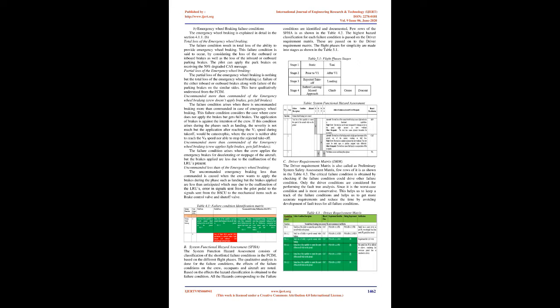Partial loss of the normal wheel braking. The partial loss of the ability of the normal wheel braking to provide braking is considered. The failure condition occurs by the loss of the outboard brakes or the loss of the inboard brakes. The parking brakes are not considered.